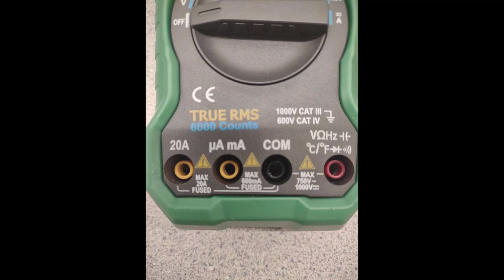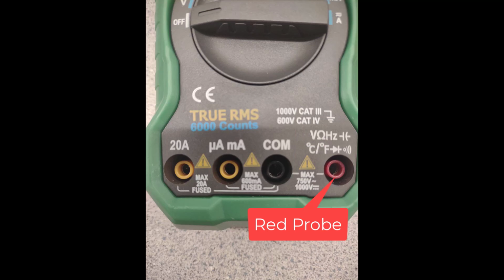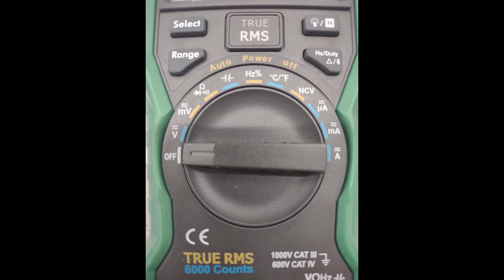Alright, so here are the ports on the green multimeter. You have a common one, and that's where our black probe is going to plug in. And then you can see here, you have voltage, and the red probe is going to go right in there. And then we're going to look for our volts here. That's going to be both in DC or AC, because you can see that straight line and then a wavy line. That means DC and AC.